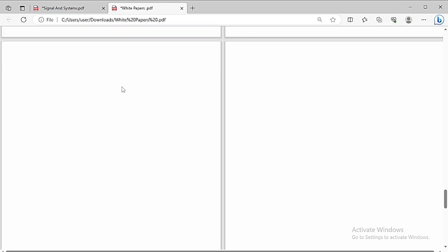So this is the continuous time Fourier transform, this is the discrete time Fourier transform, this is the Laplace transform, and this is the Z transform. The continuous time Fourier transform is going to exist when f of t is absolutely integrable, meaning the integral from t equal to minus infinity to plus infinity of mod of f of t dt. If it is absolutely integrable, then only the continuous time Fourier transform exists.